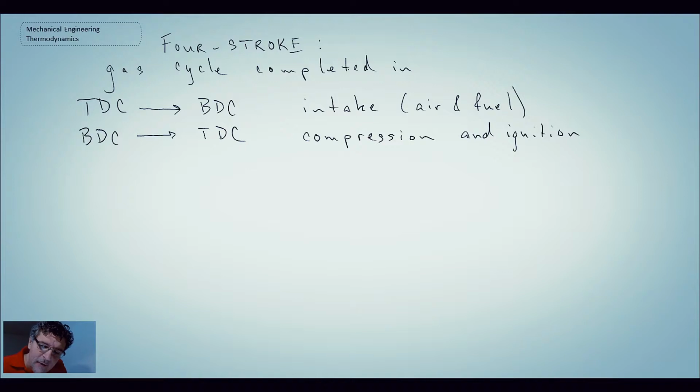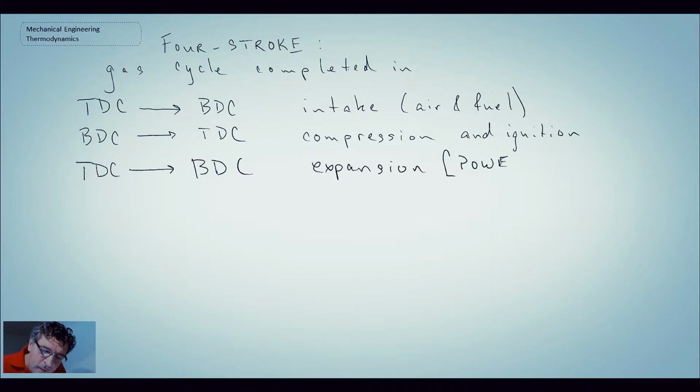And then we have combustion taking place inside of the engine. So we're going from top dead center down to bottom dead center, and we call that the expansion stroke. This is really where we're getting our power from. So that's the power producing stroke.